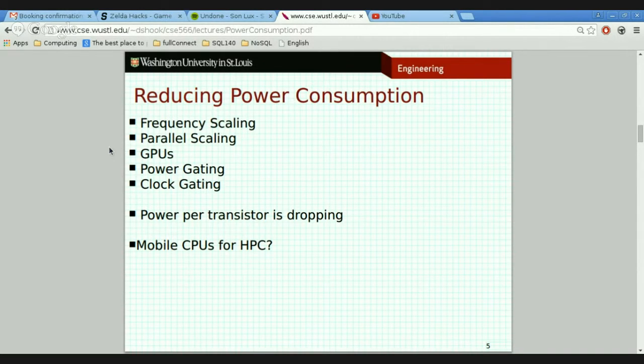In addition to that, as transistors get smaller and smaller, the leakages from these transistors get worse and worse. And that's actually where a lot of the additional power consumption is coming from these days, is all of those transistors, every transistor leaks power. And so the more transistors you have, the more leakage you're going to accrue in your CPU.